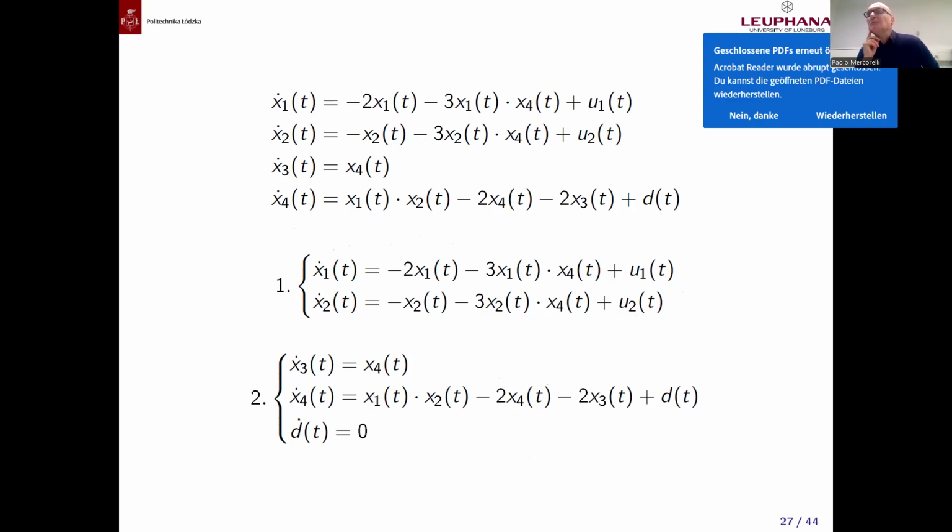But it could be that also in this sense, sometimes we have advantages in one representation, some advantages in the other one. It depends. Do you remember in one case we have the condition u not 0, the derivative of the current not 0. And when I split, we had the condition current not 0 and the derivative of the current not 0. But the current physically came from a voltage. This means the conditions are the same.